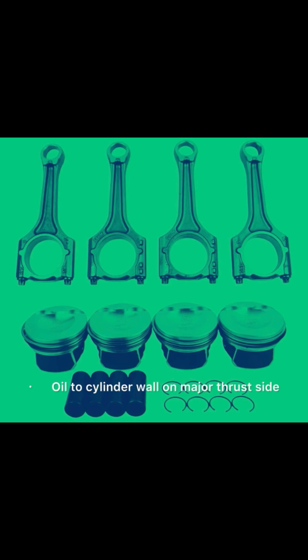20. What inspections can be done to connecting rods? Straightness, bore alignment, cracks, size, taper, out of round bores, bearing wear, visual inspection, discoloration. 21. What types of reconditioning can be performed on connecting rods? Resizing big end bore, replacing fasteners.